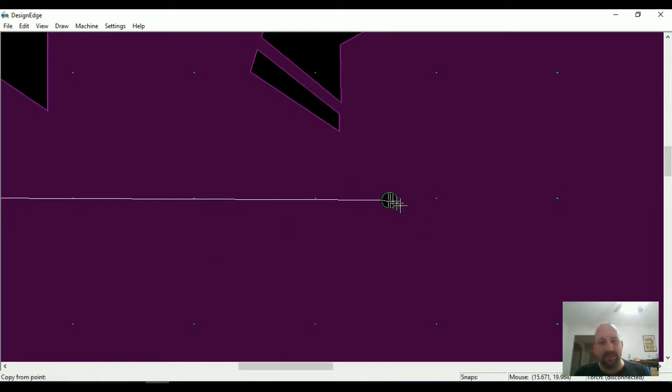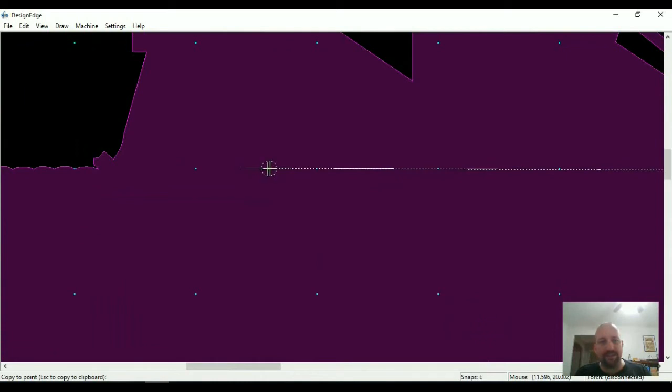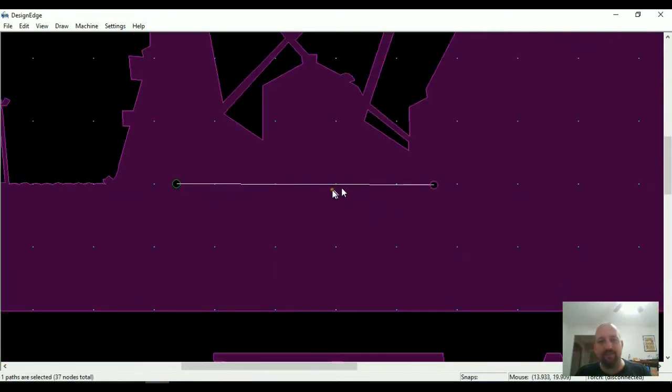I'm going to C copy that circle from a C center point. And to get the center of something, you have to click actually on the shape. So I'm going to click on it, and you can see I've grabbed that circle by the center. And I'm going to move down here and E endpoint snap it down there. And I'm going to offset, and I could either do 0.125 divided by 2, or I could type in the 1/16 of an inch, 0.0625.